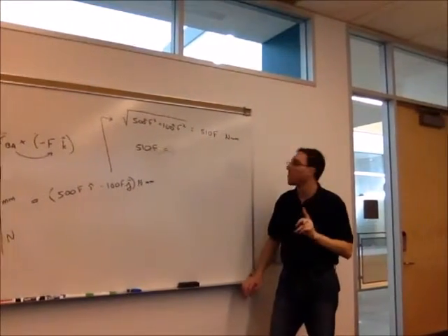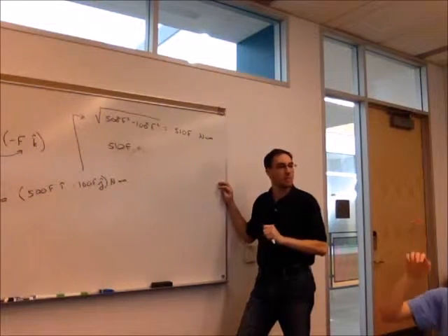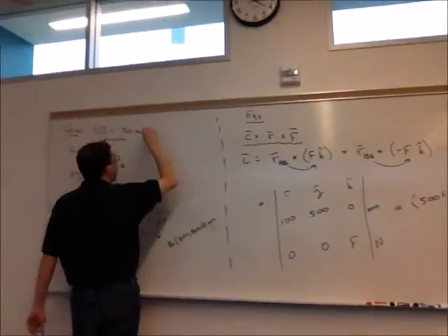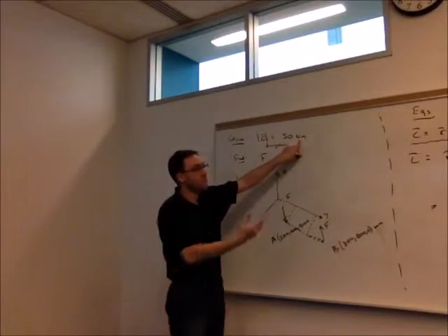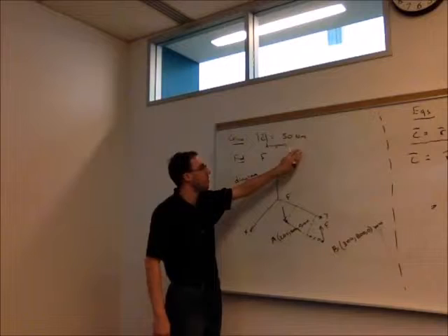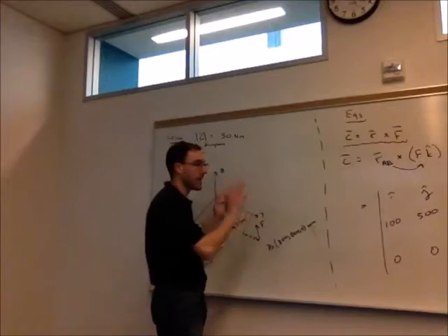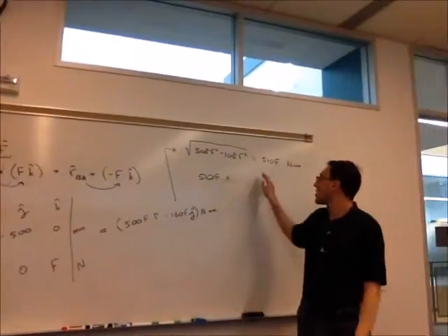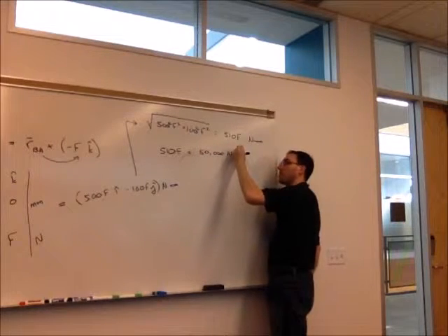Now here we want to be careful for one more thing. What do we have to do before I equate this to something? Right, this is in Newton millimeters. This was given to me in Newton meters. For metric, it happens less frequently that you have these two different systems of measurement. Here we do have to convert everything to the same, either both Newton millimeters or both Newton meters. More commonly in English problems, this might be given to you in pound feet, and we did all of our calculations in inch pounds, in which case we again have to choose one or the other. I'm going to keep it in Newton millimeters because that's already set here. So instead of 50 Newton meters, it'll be 50,000 Newton millimeters on the right-hand side.